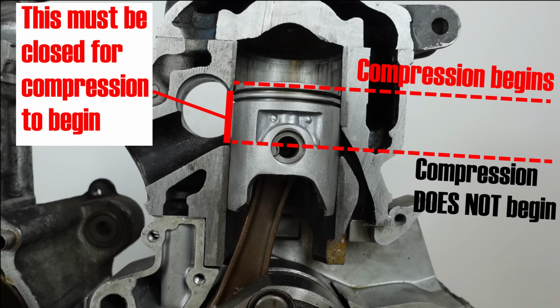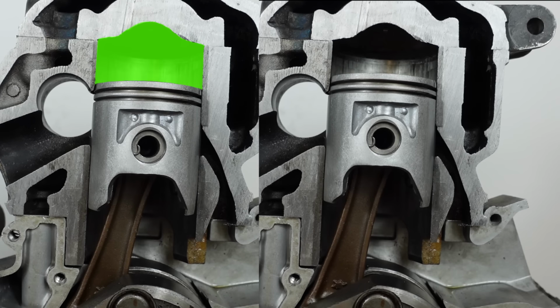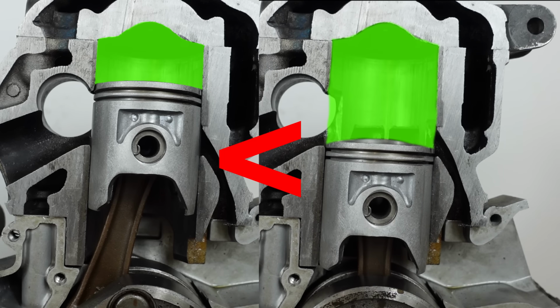This is why in a 2-stroke, the compression ratio, or the ratio between the largest and the smallest cylinder volume, is the ratio between this and this volume. Obviously, this is much smaller than this and leads to a much lower compression ratio, which ultimately limits efficiency and performance in a 2-stroke engine.